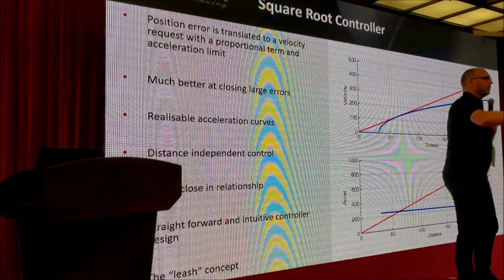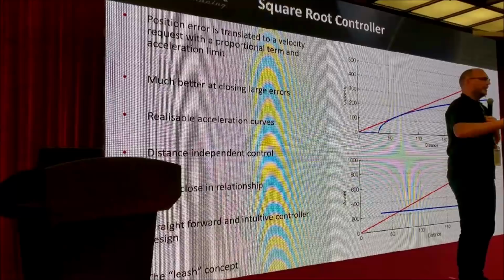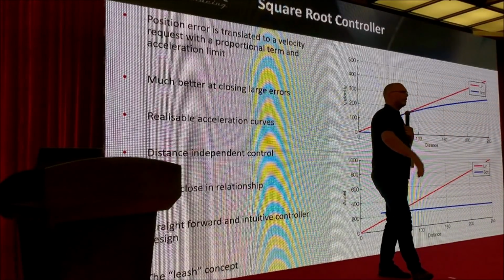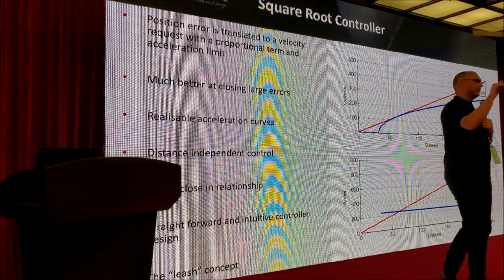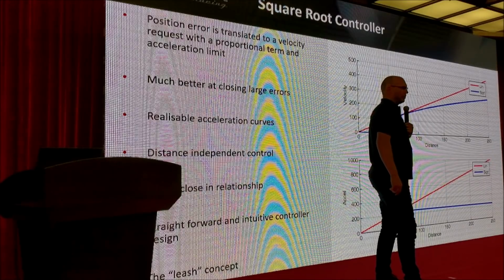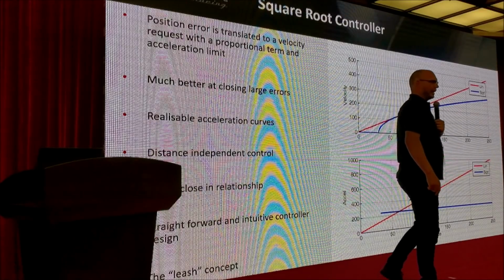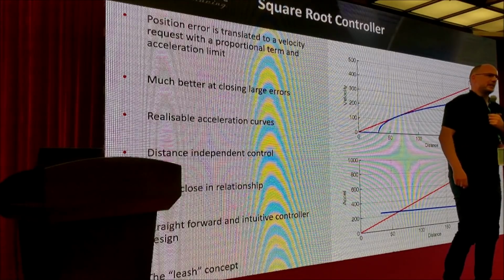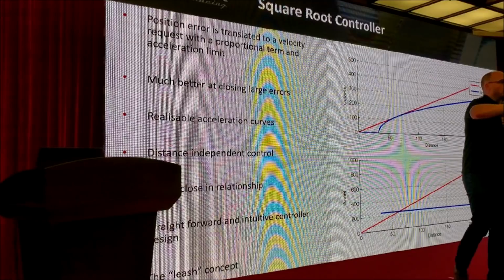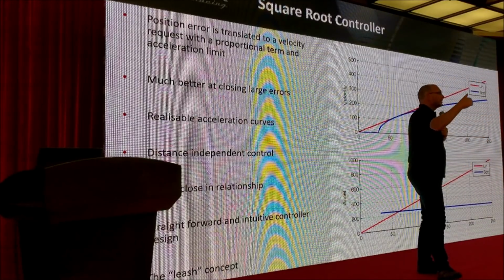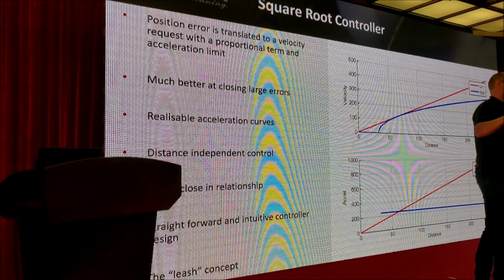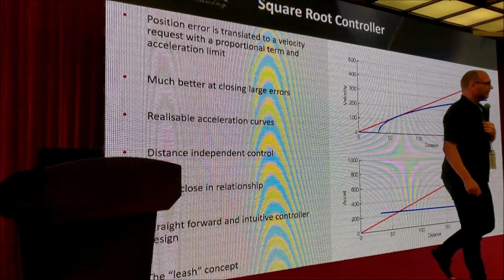If I'm 50 meters from the stoplights and I'm doing 50 kilometers per hour, I can stop very comfortably, put the brakes on, no problems. If I'm 100 meters from the stoplights but doing 100 kilometers an hour, all of a sudden my passengers are getting very, very scared, because the distance it takes to stop with a constant acceleration is the square of the velocity.